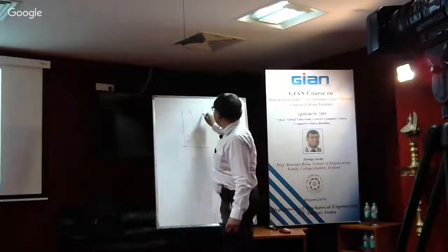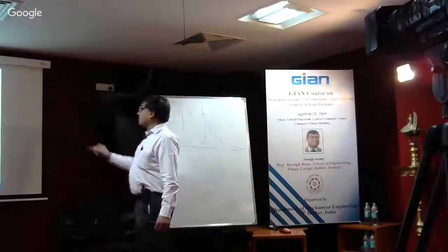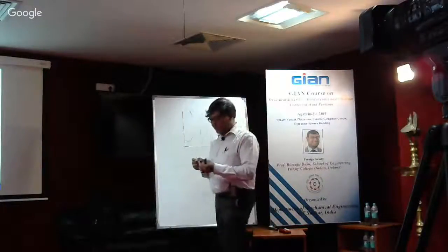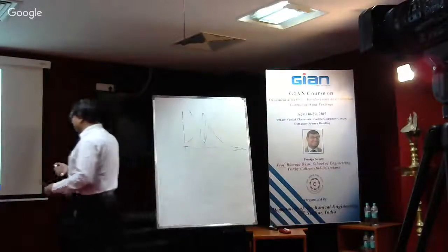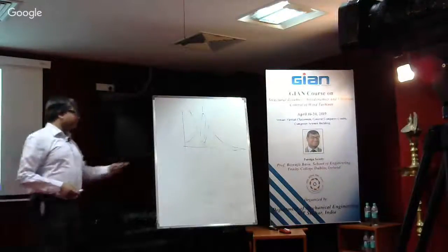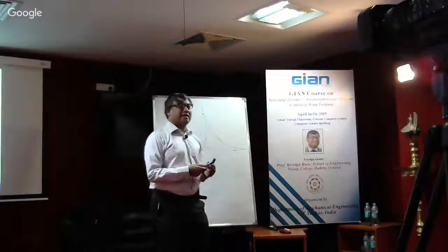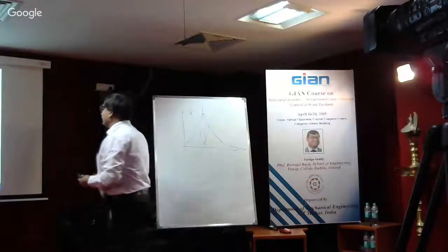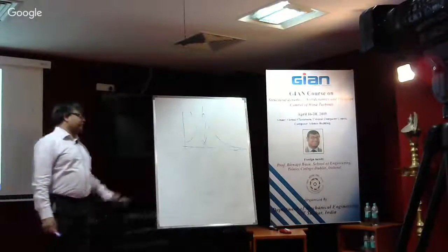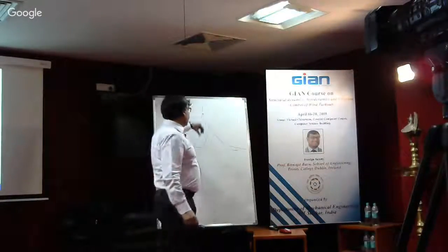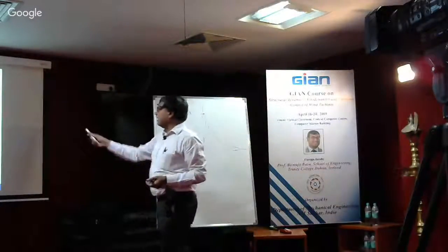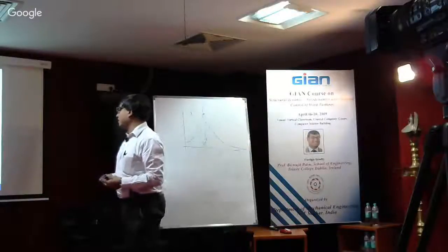So there's a peak at the denominator over here. So that has to be actually nullified. So use an inverse filter. If you have something 0 in the denominator or close to 0 in the denominator, then you get a peak here. And to combat that, you should have something inverse of that. That means what you have at the top actually nullifies this peak. This is kind of something like a notch controller, and this is actually used to prevent vibration of the tower.